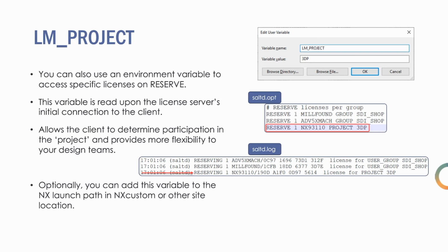It makes it really easy to adjust who is in the project. So you could optionally set this in your launch path for, say, NX custom or in a batch file. You could set this variable and launch NX that way.